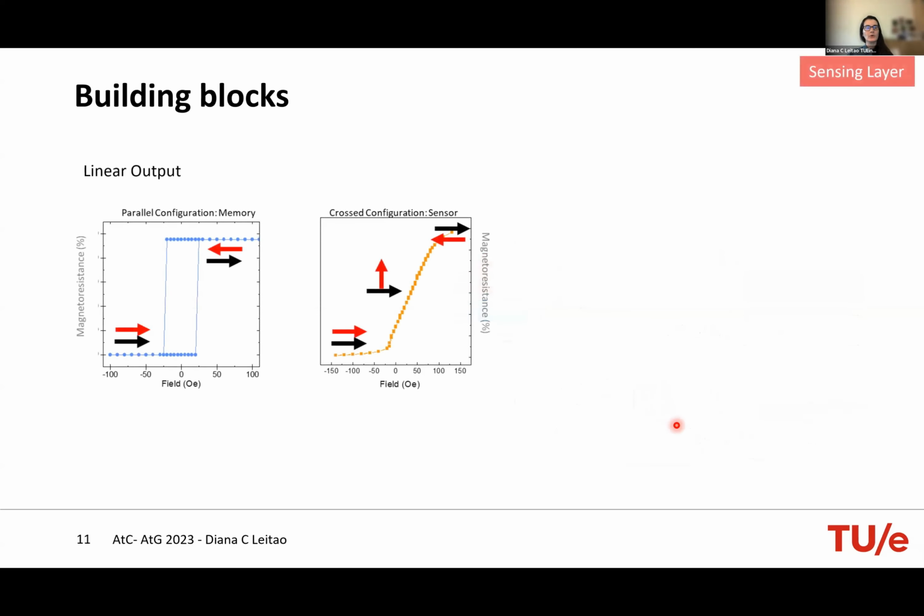And this is the key point of also the technologies that I want to share with you, is that we can start by deposition to have two different orientations of the magnetization, parallel in the low state, anti-parallel in the high state, and the transition between these two states is done via a square curve. So you just quickly switch, mostly via a domain wall, the status of the magnetization of one of the layers.